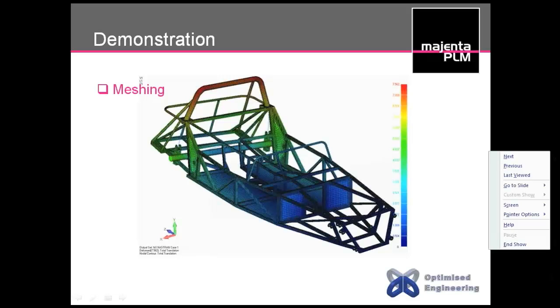One is that a complex structure like this sports car chassis couldn't be modelled if you took a solid model of it and tried to mesh it with 3D elements. You'd be there all day trying to obtain a solution, and I wouldn't really fancy that. So idealizing it, just looking at the surface representations and doing shell modeling, gives you a real performance advantage, productivity advantage.